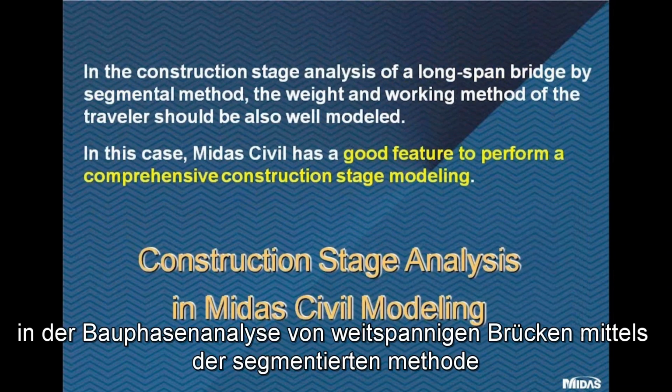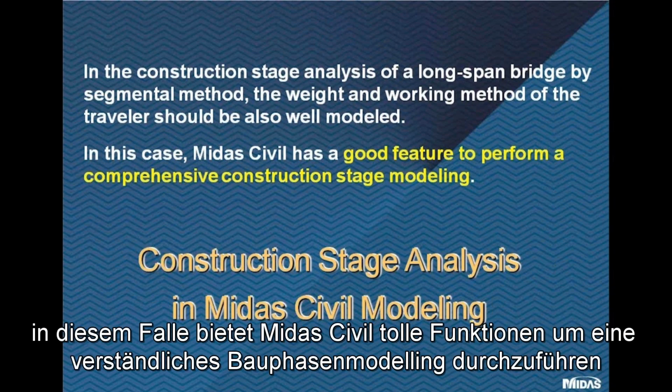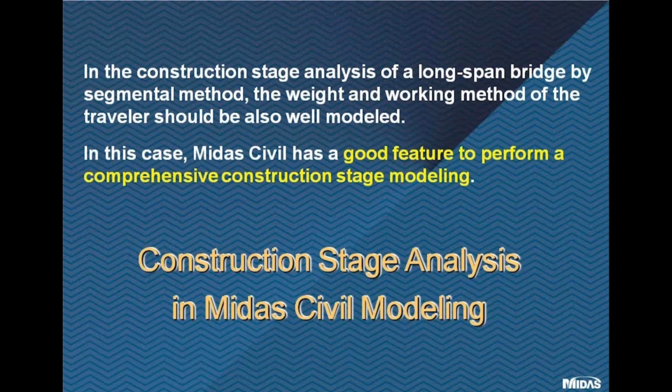In the construction stage analysis of a long span bridge by segmental method, the weight and working method of the traveler should also be well modeled. In this case, Midas Civil has a good feature to perform a comprehensive construction stage modeling.